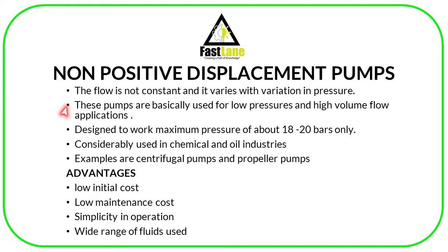Basically, these pumps are used for low pressures and high volume flow applications. So these pumps cannot withstand higher pressure applications. That's why such pumps are not capable to work against high pressures. So this is the reason as to why they are not designed for application in hydraulic systems. As we said, they work with low pressures. So they are designed to work at a maximum pressure of about 18 to 20 bars only.